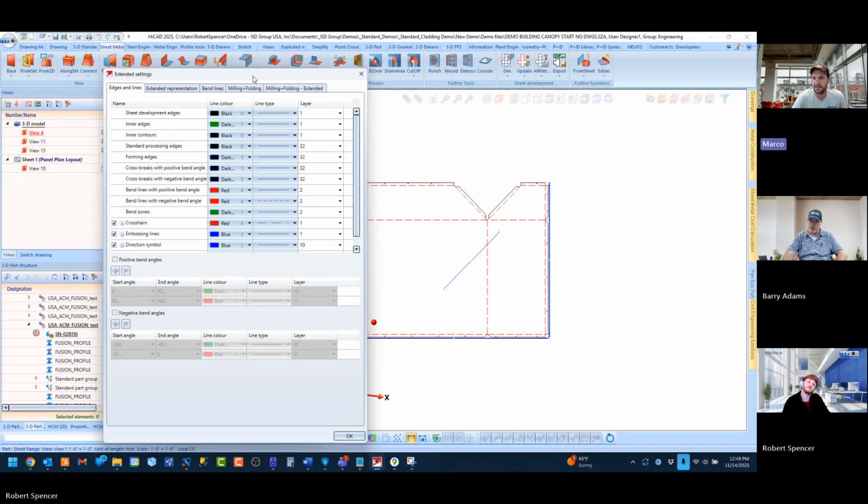He'll lay out some stuff in Autodesk AutoCAD, and I'll just import that into AlphaCam. I give that to them all in one layer as well, but I do differentiate between a groove or a fold line versus a cut path. Yeah, a cut line. It definitely doesn't hurt to separate the two different line types. Makes things a little easier for everyone to understand.